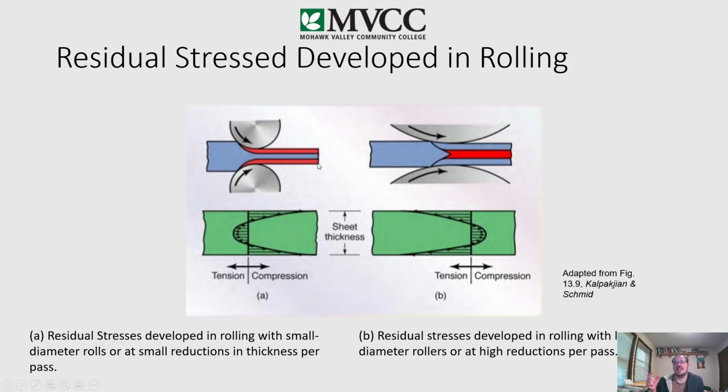So you can get a pretty high precision when we talk about hot rolled and cold rolled. One of the nice things about cold rolled is you can actually get a pretty nice precision on it, so the material's not still shrinking as it recrystallizes when it's hot. So that's kind of nice. You can get really good precisions on it, but if you were to take that and then machine it, not only does it have a higher strength, meaning it's harder to cut with your end mill or bits, it's also got these internal stresses.